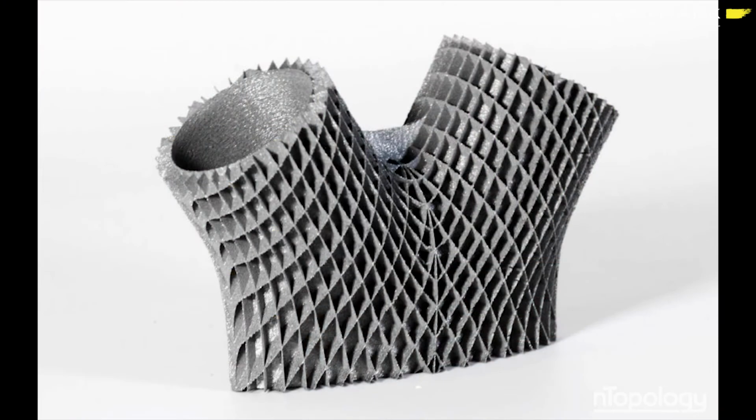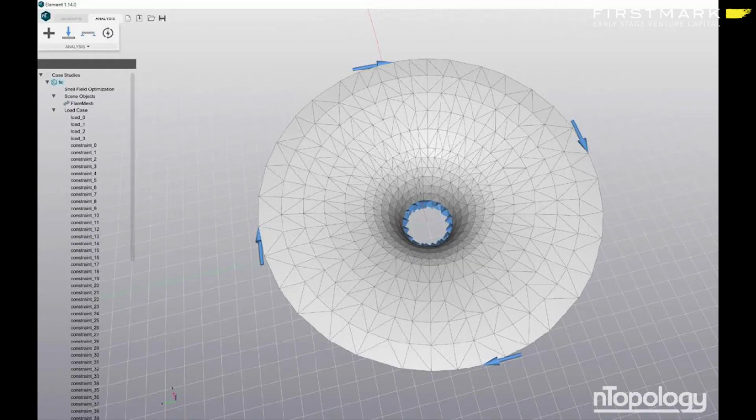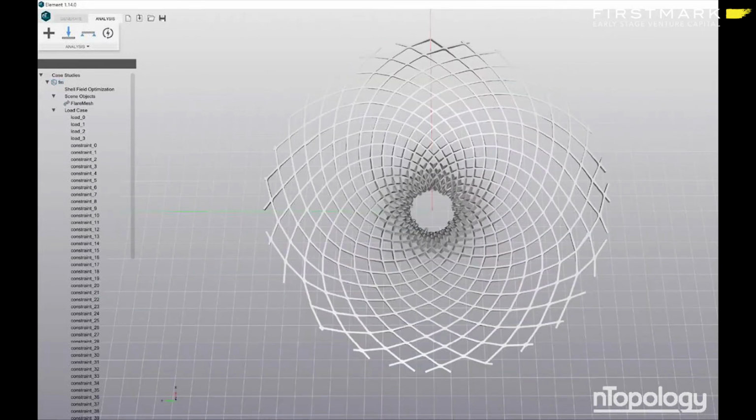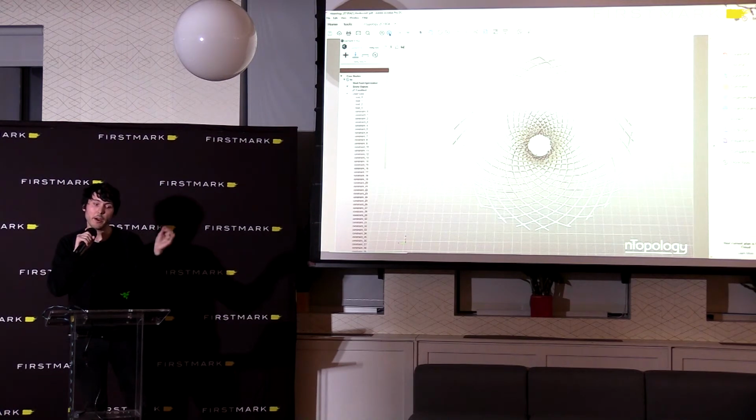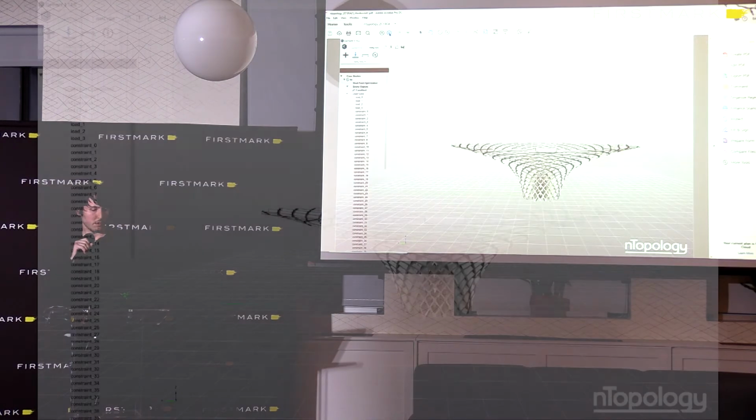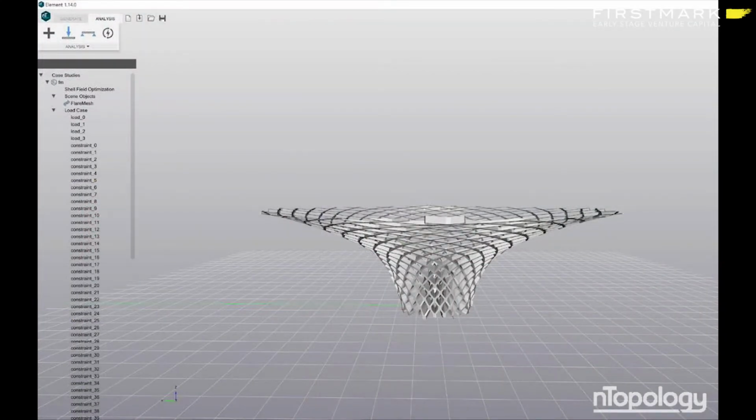And this is a connector built in the same method. And so in addition to varying properties like size and thickness, we can also vary things like orientation. And so in this case, it's a part that's being twisted under a moment, and the rib structure is now following the optimal stress paths through the part. And again, also locally, the properties are changing, the thickness, the height, etc.